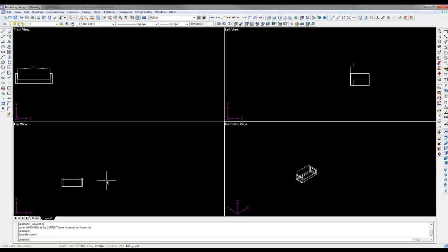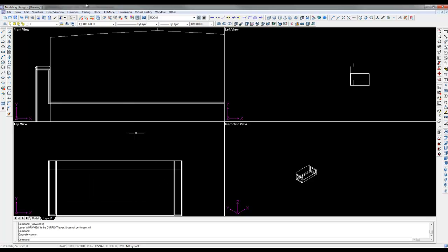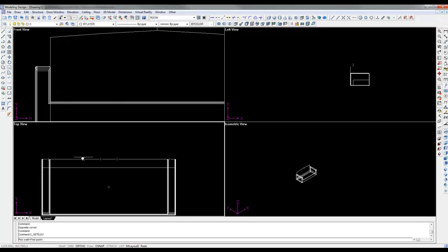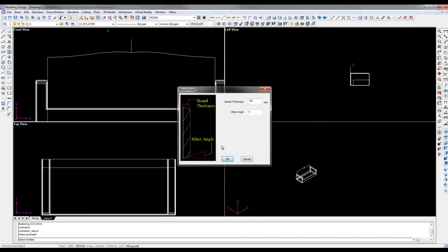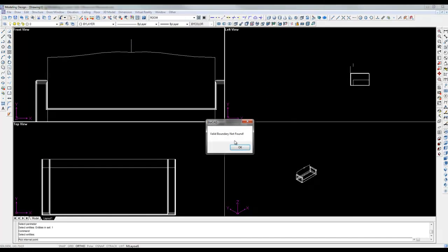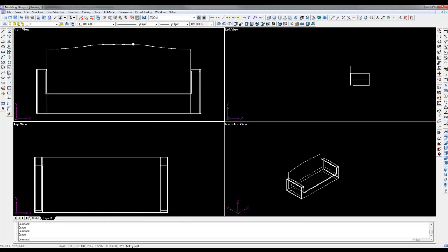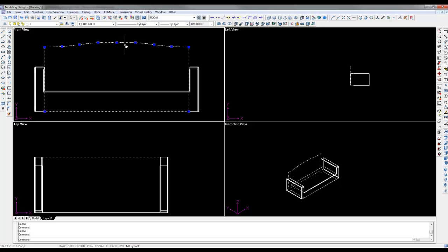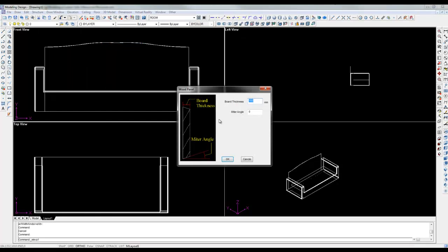There you go. And then we can try that out again. Okay. So let me just set my UCS just to make sure, and try again. Okay, so the other reason it's not working is because the polyline's not closed properly. So PE, enter, for polyline edit, C to close. And now if we do it, it should work.